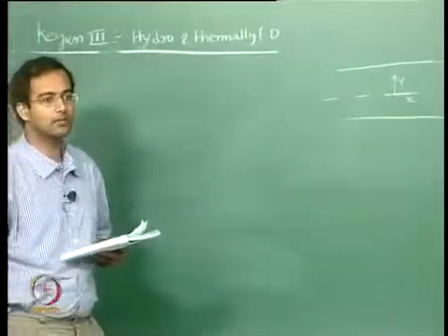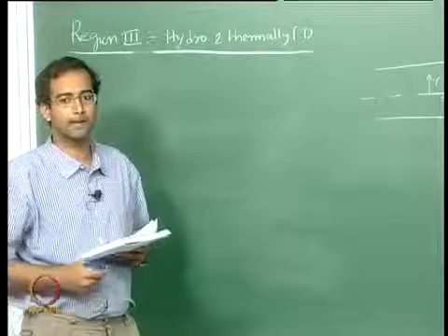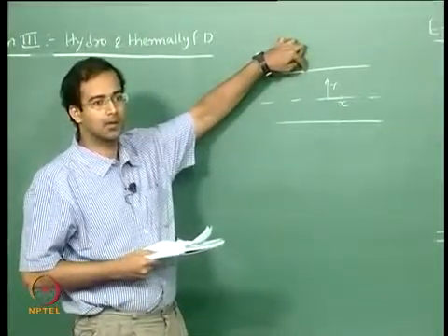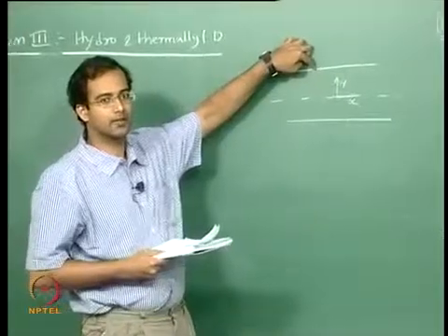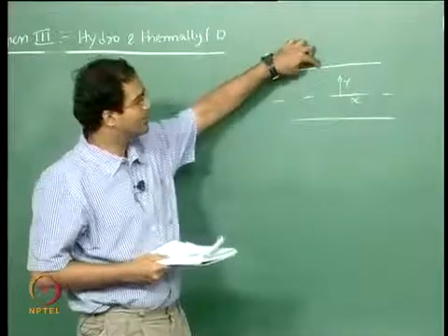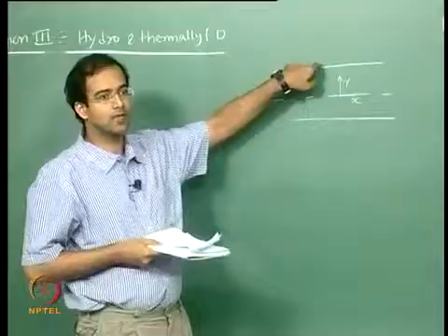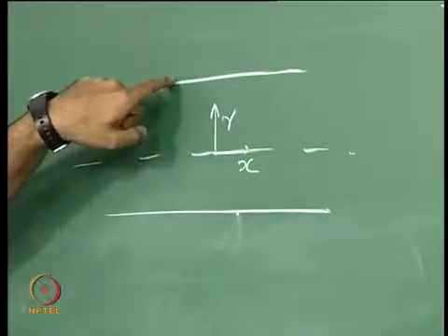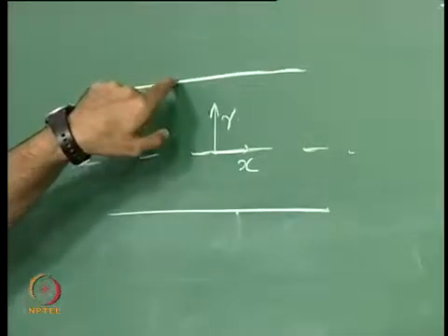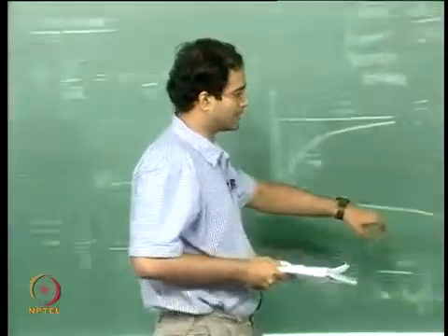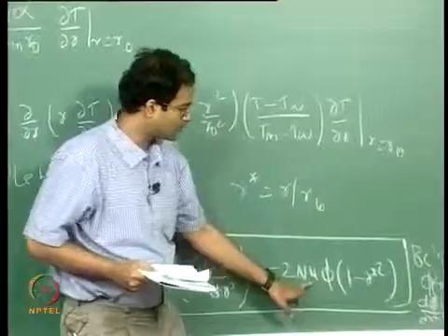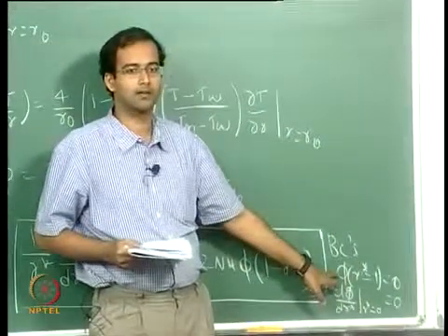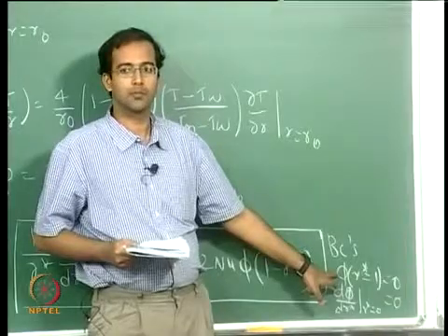So what I would like to do is, when you solve this with the shooting technique, you can start working from the coordinate system which starts from the wall. Why we can do that is that at the wall you do not know the gradient. The gradient is related directly to your Nusselt number. So in this equation you do not know what the Nusselt number is, and you also do not know the gradient at r star equal to 1, correct? So both are not known.